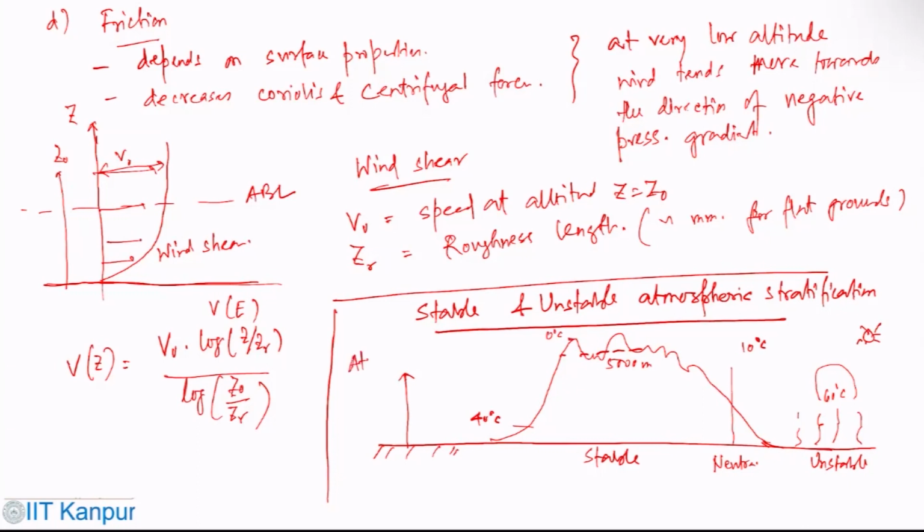So this is my atmospheric lapse, which is typically 1 degree C per 100 meter. So if the ambient air gets cooler, slowed down 1 degree per meter, it means that the atmosphere is stable. If it gets cooler faster, it is unstable. Atmospheric lapse plays an important role.